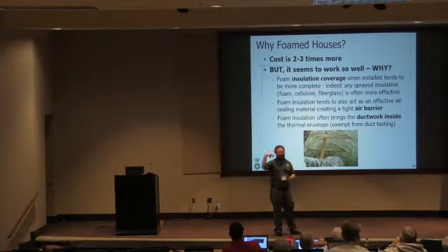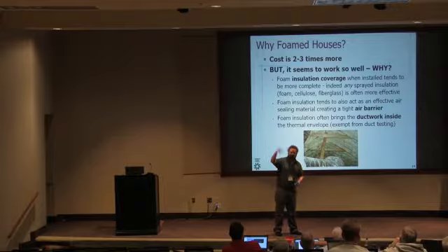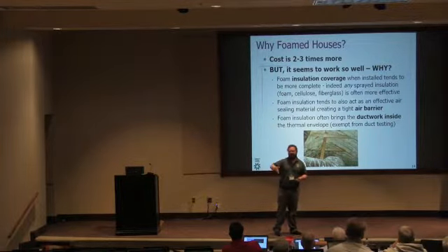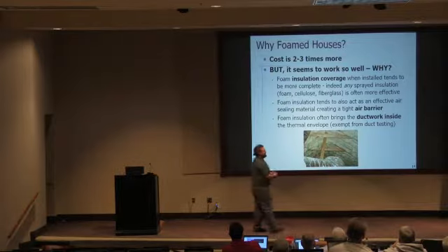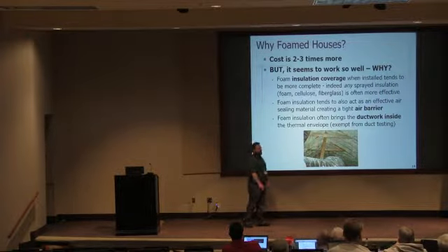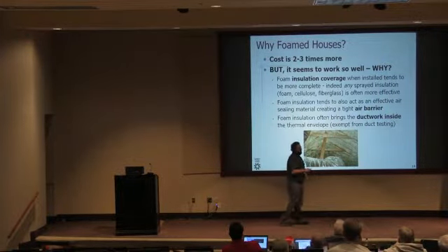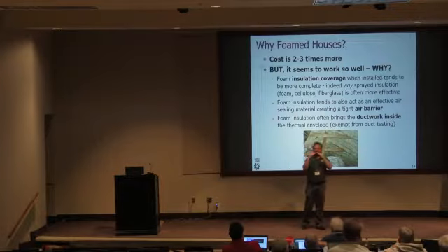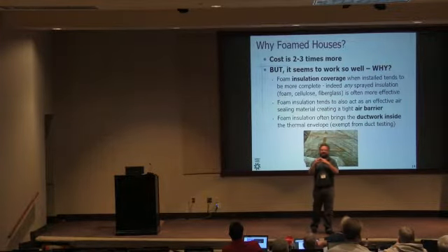If my drywall and my ceiling is my air barrier, and I punch a boot through it for HVAC, I punched a big old hole in my air barrier, that has to be sealed as well. That doesn't happen until final, right? So everybody along the way has to be air sealing to make your insulation work effectively. All of these trades have to be coordinated. The nice thing is that you've got one installer that puts in complete insulation, and that insulation is also your air barrier. And then in addition to that, one of the big benefits is you bring that ductwork inside the conditioned space.